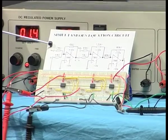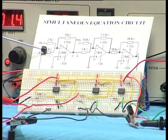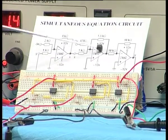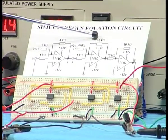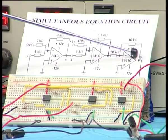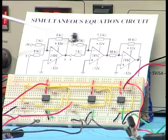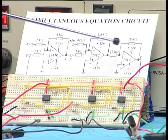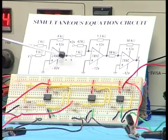There is a minus 5 volts here, the 2k resistor, 4k resistor, and the y is coming all the way from the output of the third amplifier, and this is the first amplifier which gives me the value of x, and this is the second amplifier which has got 470 ohms with a plus 2 volts and 1 kilo ohm and 1.5 kilo ohm as a feedback resistor, and this is the inverter with a 10k resistor here and the 10k resistor here, so that the minus y becomes plus y, and thus plus y is again fed back to this circuit, so that once I wire the circuit with all these values, if I measure the voltage here, that will give me the value of x, and if I measure the voltage at this point, I will get the voltage y corresponding to the solution x and y of this equation.